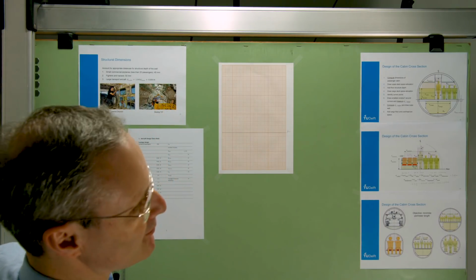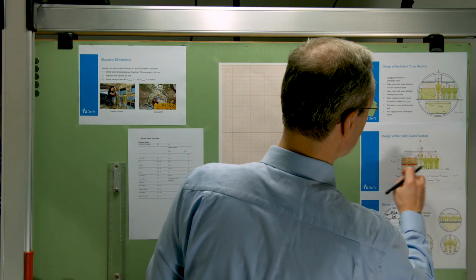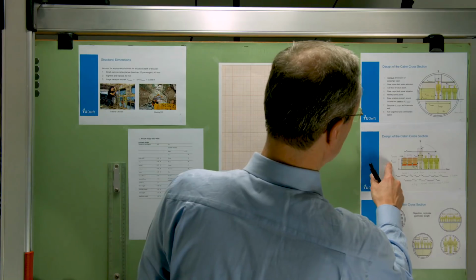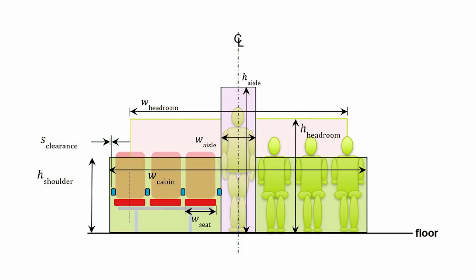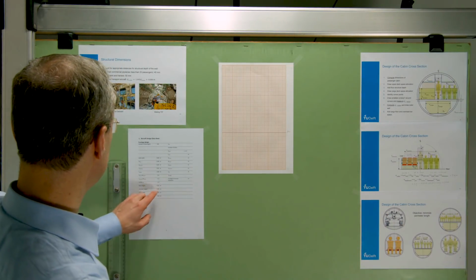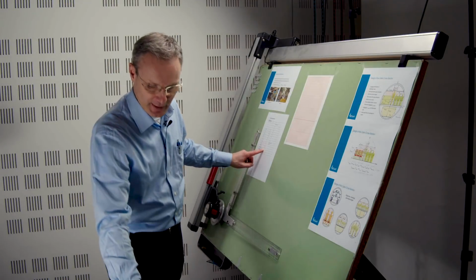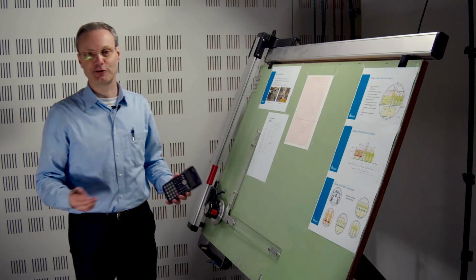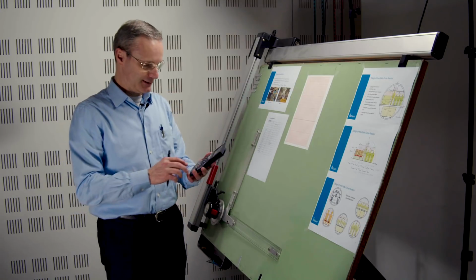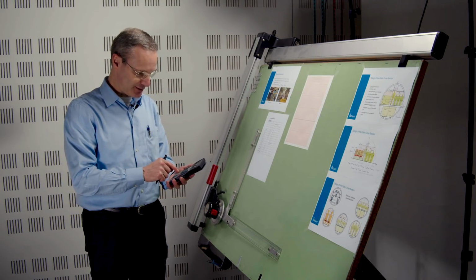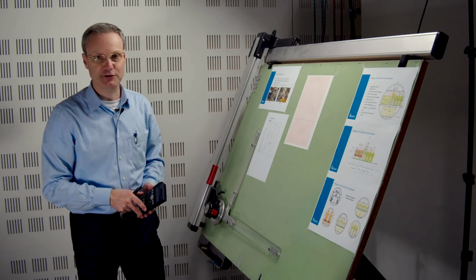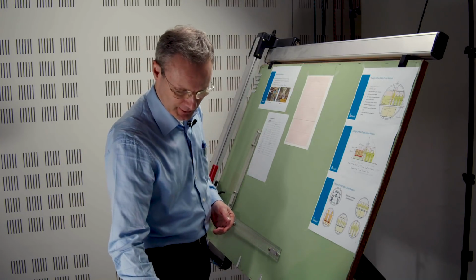And now what we're going to do, we're going to define all these blocks, all these rectangles, on the basis of the data we have so far. So the first one is that we will have a shoulder height, because that will be the height of this block. So I'll like to draw this line here. And the shoulder height has been given as 95 centimeters. Now, 95 centimeters has to be converted into the scale of this drawing. And the assignment of this exam said a scale 1 to 25 scaling. So I have 95 centimeters and divide that by 25. That means 3.8 centimeters or 38 millimeters.